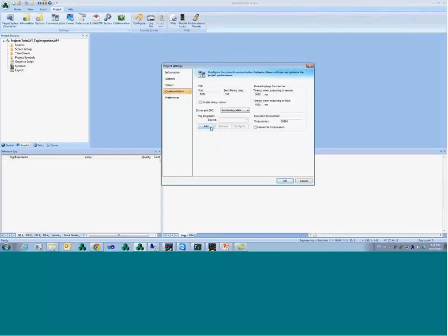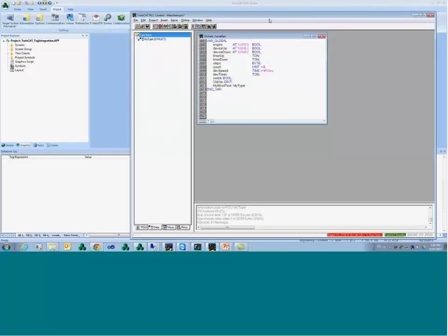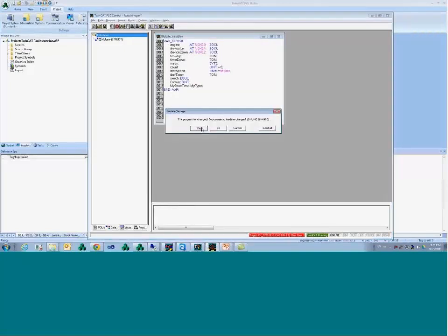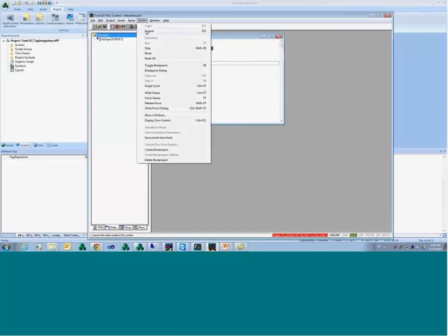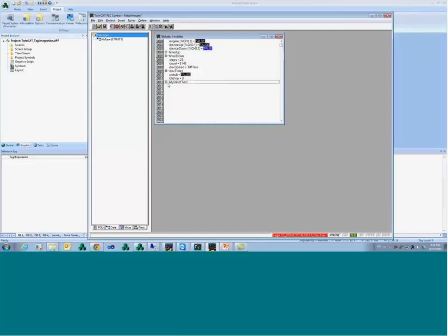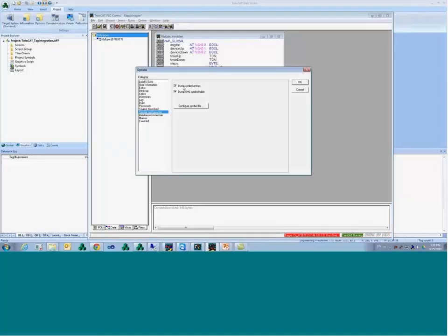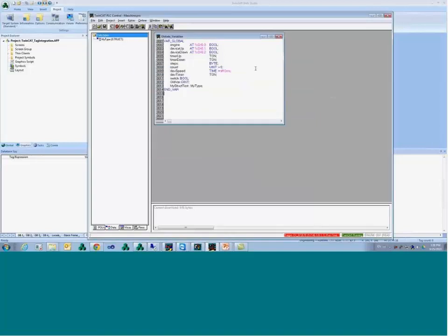So which file am I going to communicate with? I have here this TwinCAT project, the Machine Pro. Let me see. I have created this one. I'm talking to the PLC, and I have a few tags here. So I'm going to go and build this. The first thing I have to do is, under Options and Symbol Configuration, make sure that we have these two checked. Maybe we don't need both of them, but I always check. I know it doesn't hurt. And then Project, Rebuild All. When you do this, it is creating the symbol file.